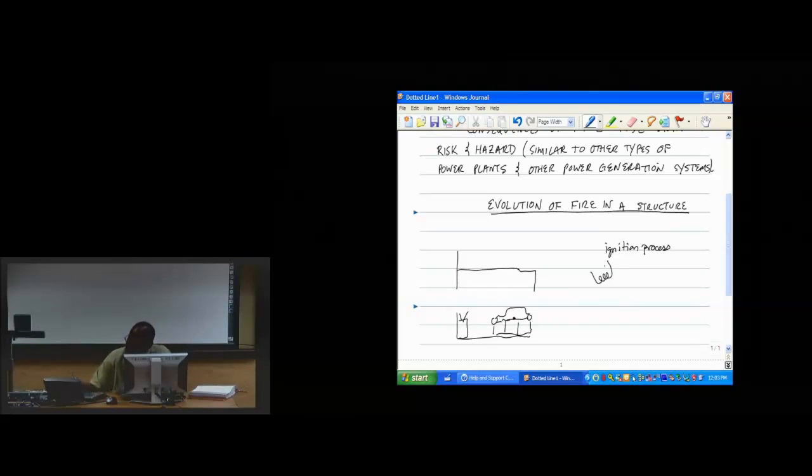What happens here is that the heat transfer process from that heat source, a hot resistive element in the case that I've abstracted, heats up the polyurethane or whatever polymeric material we're looking at. And there's a so-called pyrolysis process that occurs in depth.